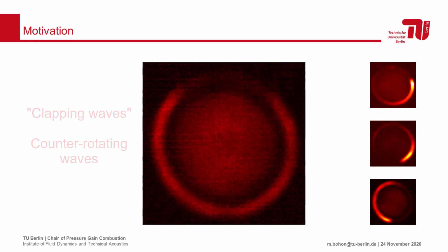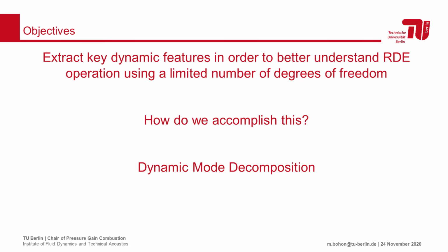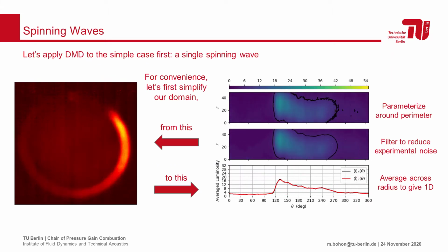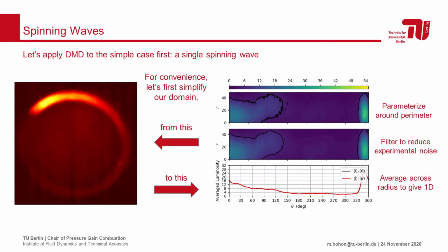same speed. In this work, our objective is to develop the tools to extract key dynamic features from the operation of this combustor with a limited number of degrees of freedom. We would like to do this using the method of dynamic mode decomposition. We begin with the simplest case of a single rotating wave.